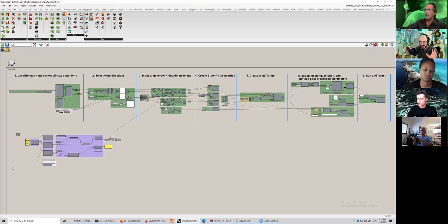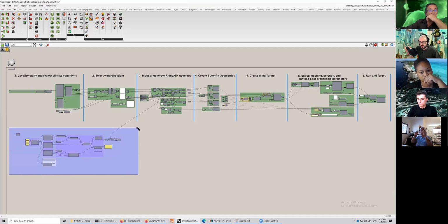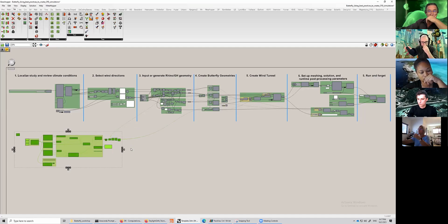First, we are focusing on outdoor studies, outdoor wind simulation, right? There is no indoor here. All the volumes are closed, right? We are doing some buildings and wind around them. And they are simplified, we call it an isothermal circumstance, where temperature doesn't play a role in a way. It's just wind, it's just the wind effect. So everything is sort of simplified, but still this applies to almost all outdoor studies, even in practice, in my projects, this is how it would be.